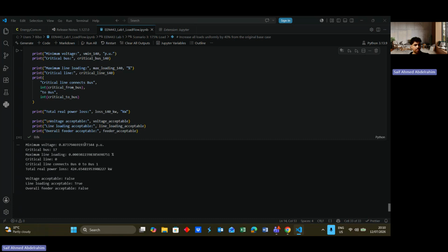This lab helped me understand how Panda Power can be used to model a radial feeder and also run power flow calculations, also analyzing the voltages, losses, and line loading. Overall, voltage support devices, feeder reconfiguration or additional feeder supports may be required to improve the system.